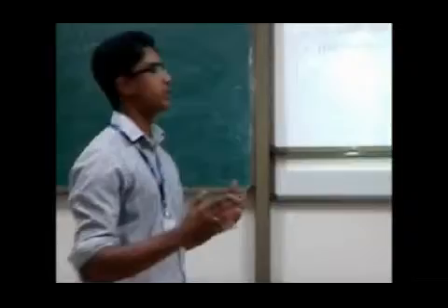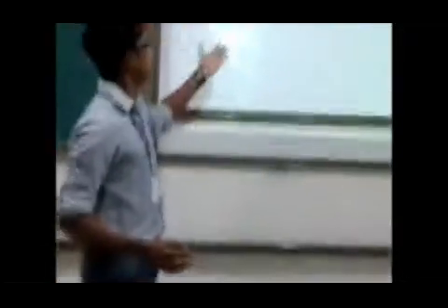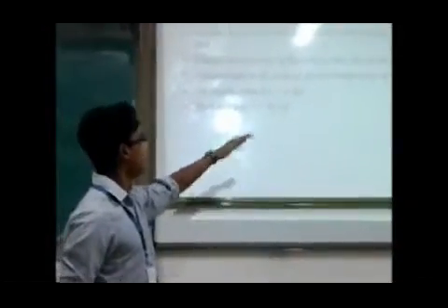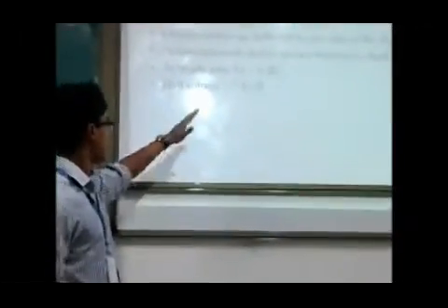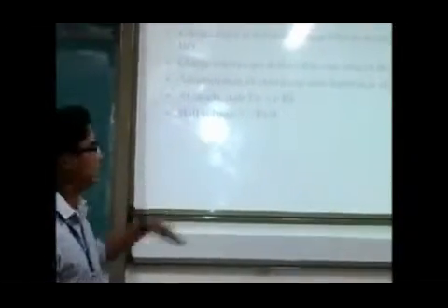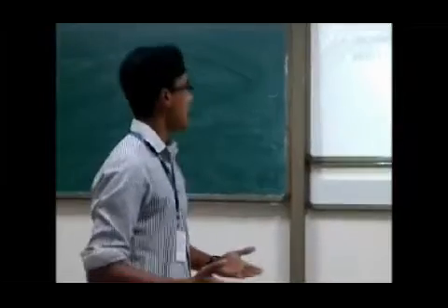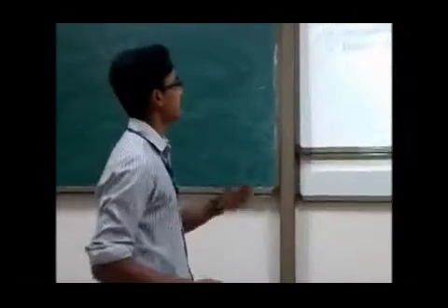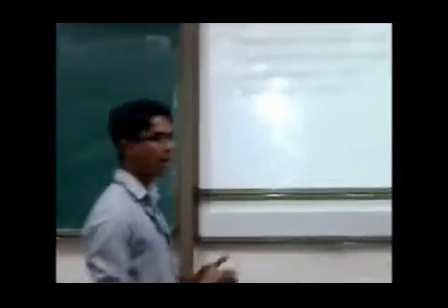Direction, the electric field will be in such a way that as time passes, the electric field will try to neutralize the magnetic field. So after some time, a steady state will be reached. Then Ey will be equal to V into Vz. We can show the derivation for this, and when steady state is reached, Ey will be equal to the magnetic field term. That is, the electric field will neutralize the magnetic field, and this electric field is known as the Hall field.